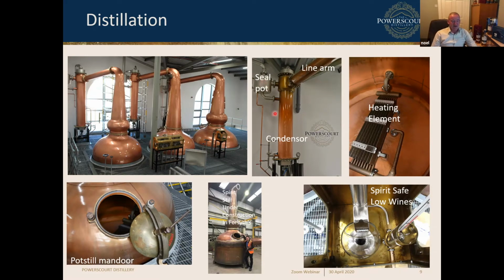The last two photographs is the safe, the one on the right, and here you can see the stainless steel pipe through which the spirit comes, and the spirit flows into that glass bowl and down through the pipe out to a receiver. But there's also, you'll notice, a small stainless steel pipe coming from the bottom of that larger one, and that drains across into a glass tube where the spirit's allowed to fill up the tube, and it will raise the hydrometer in there depending on the alcohol strength. The higher the hydrometer floats, the more it gives you an indication of the alcohol content of the spirit that you're measuring. There's also a thermometer there, because the temperature and the density are related to give you the correct reading for alcohol.